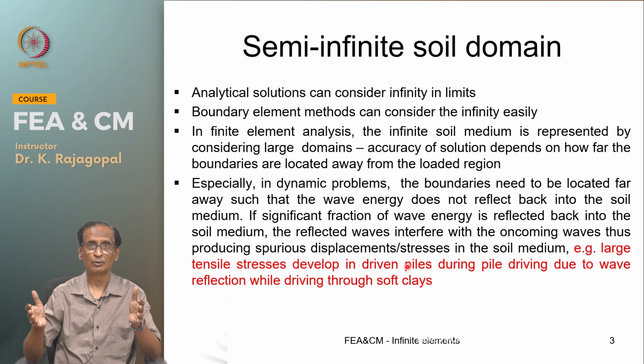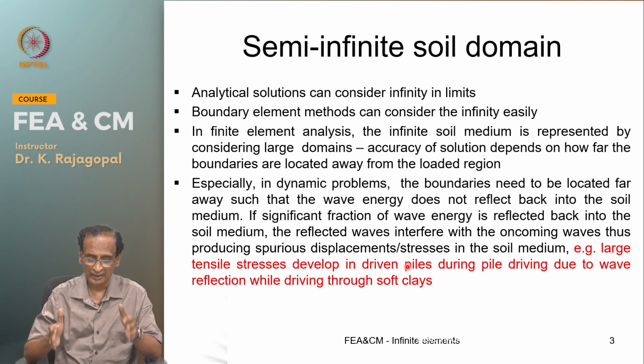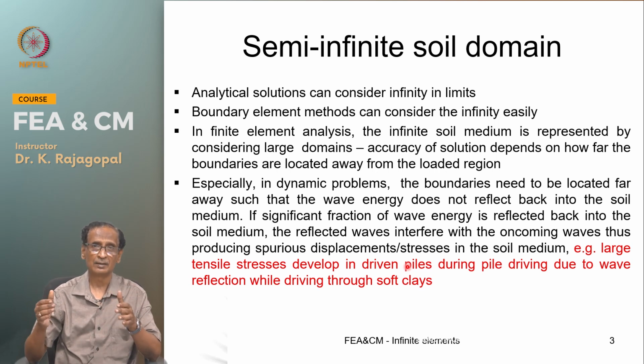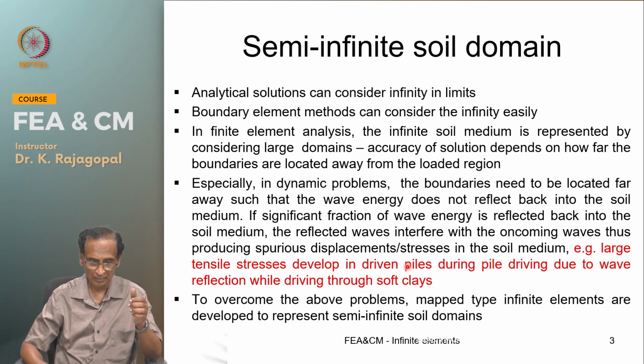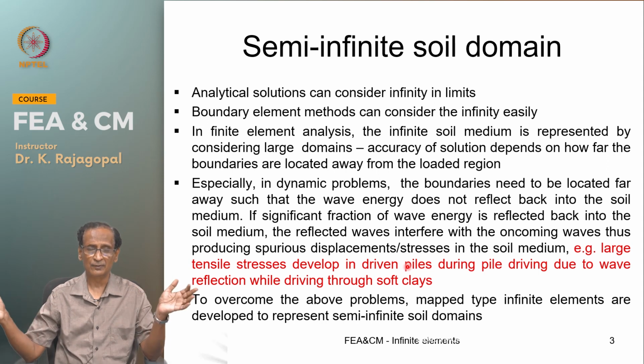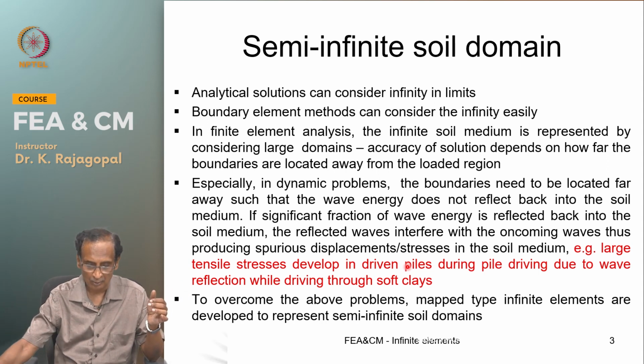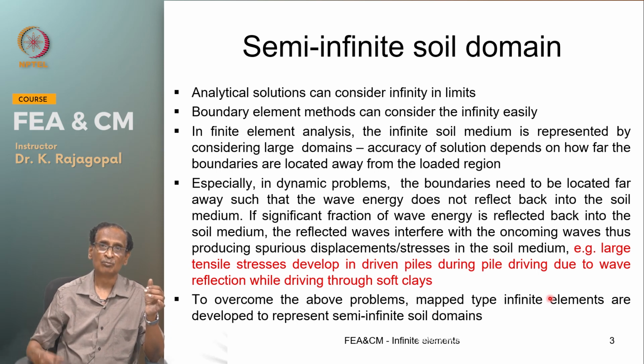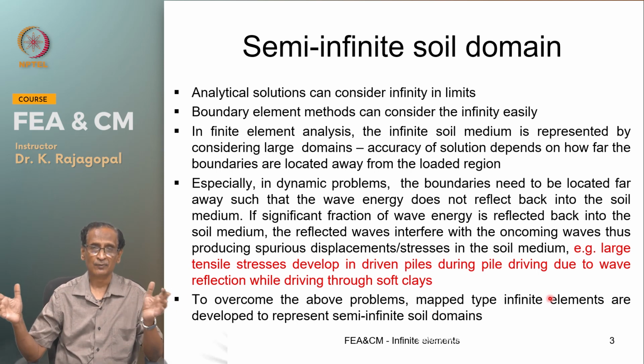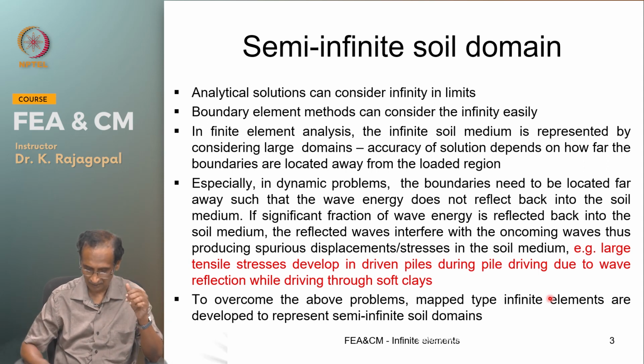And the same thing happens even in the case of finite element analysis of our geotechnical problems. And so, we need to take the boundary very far away, and to overcome that, now we have these map type infinite elements that can represent infinite soil medium by using one simple element, that we will see in this class today.